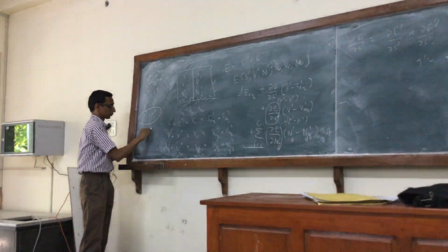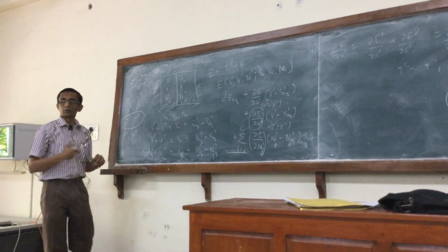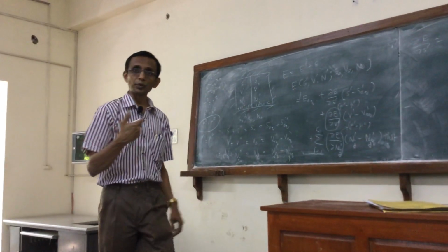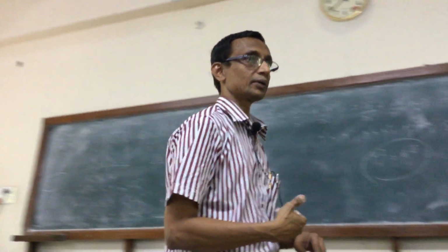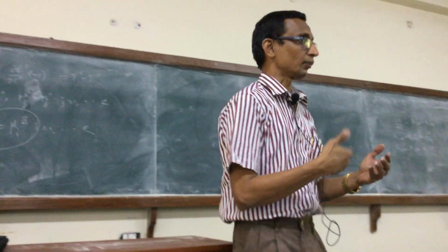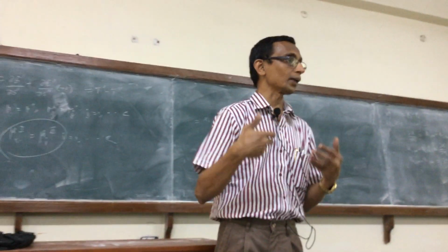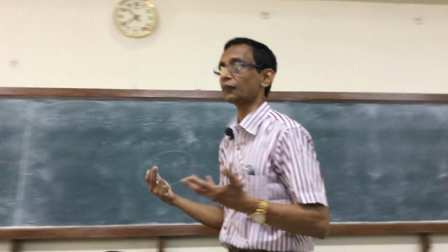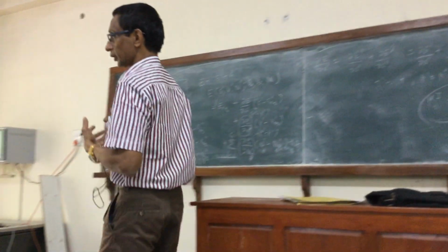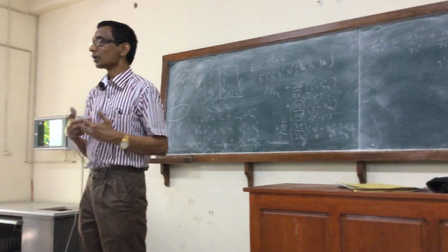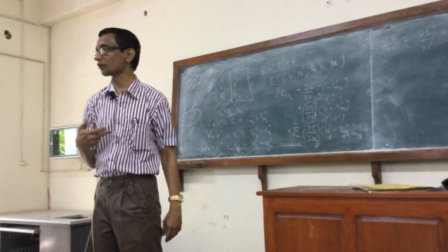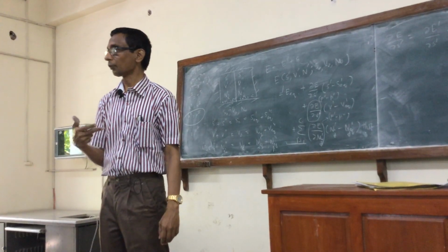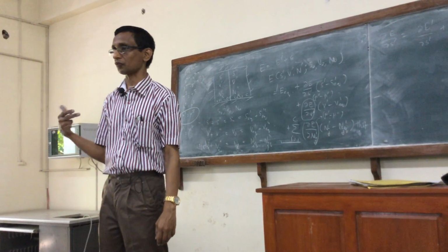So we went to the departure function, calculated mu V minus mu IG. Then we went to the same departure function, calculated mu L minus mu IG at the same temperature and pressure. And we then equated the two. And so here again, we need expressions for the chemical potential in terms of an equation of state.